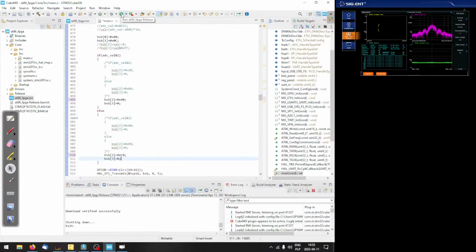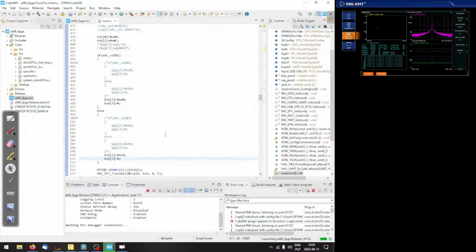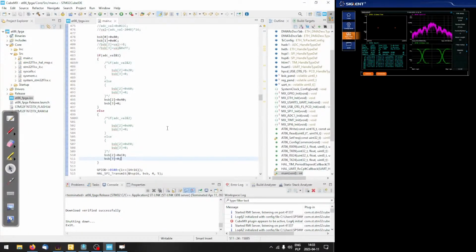So if I actually try and program the microcontroller with this code, we've got the carrier, the spectrum analyzer. And after doing that, yeah, we should get rid of the DC component, and the PSK mod should be saved and it's now fixed. Yeah, so the problem was in the arithmetic, because I just calculated the wrong values for the phase words. So for BPSK, we got plus and minus 90 degrees phase shifts.